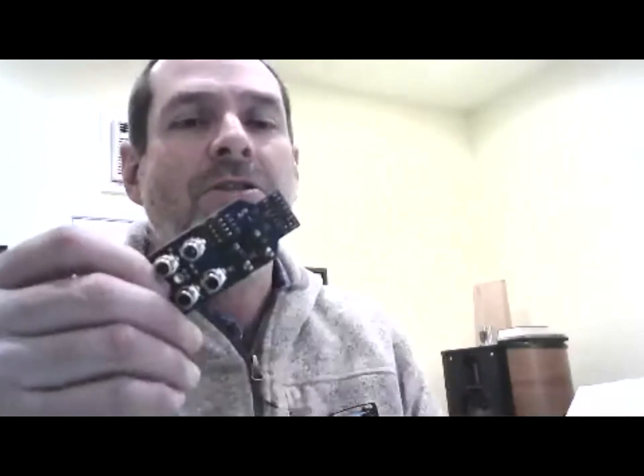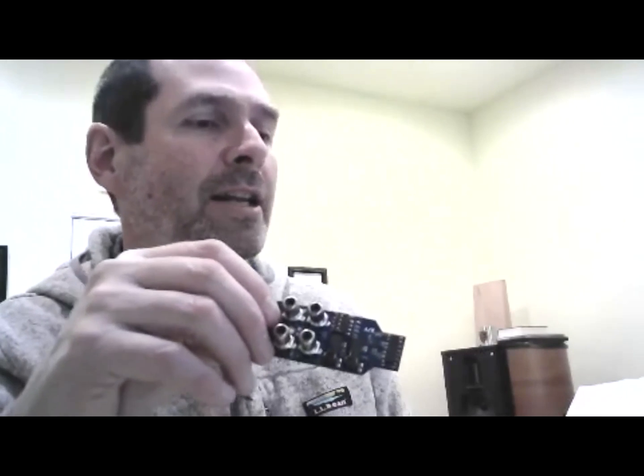And so the best audio recipe is to use the full span 3.3 volt 124 ohm DAC with PWM oversampling using that smart pin mode. And you get really good audio out of there. It's super low noise in the background. For our ears' purposes, I think it's like 16-bit quality. It works pretty well.